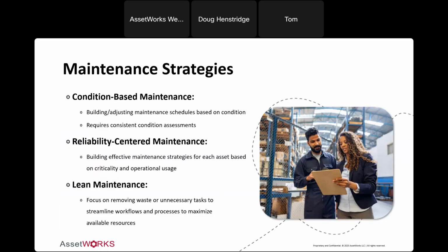The other things to consider are, do I do maintenance based on condition-based maintenance? A number of years ago, I worked with a customer. They had a criticality factor in their preventive maintenance, where a new piece of equipment received an inspection on a semi-annual basis. As that piece of equipment aged, its condition slipped from new, excellent, to good, and they shortened that inspection schedule to quarterly.